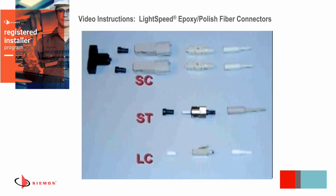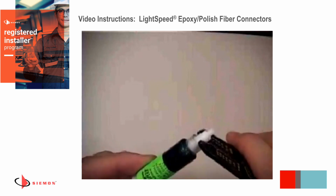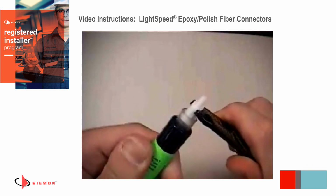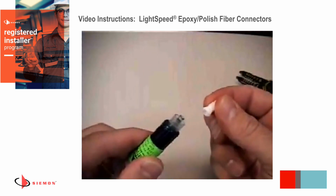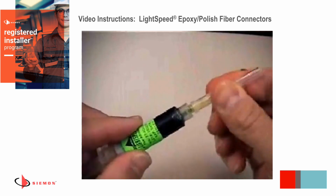All connectors consist of several components: a strain relief boot sized for the 900 micron buffered fibers, the connector body, and the dust cap. The SC duplex connector, as shown here, also includes the outer housing and duplexing clip. Prepare the adhesive syringe by unthreading the cap and installing the metal syringe tip provided. The nose of the jacket stripper tool may be used to assist in unthreading difficult syringe caps.